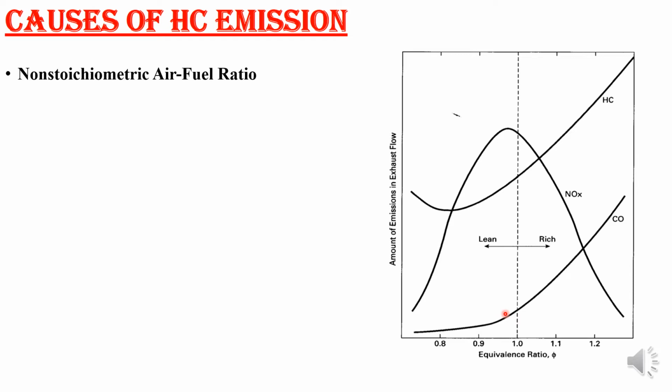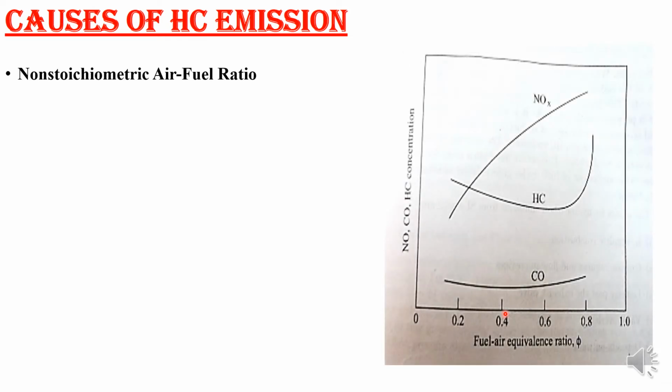Okay, next, we will go for soot emission. This is another way. Same thing, how it will be on the lean side for your diesel engine. In a diesel engine, after around 0.8 it will give soot, like anything. So this is for a diesel engine, earlier was for an SI engine. Soot will be like anything in a diesel engine after 0.8, because a diesel engine always works in a lean region. More amount of air will be supplied because of the heterogeneous mixture, so always it will be the lean region itself. A richer region we won't find in a diesel engine.